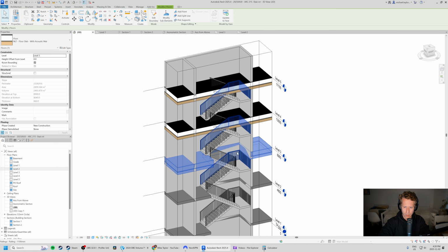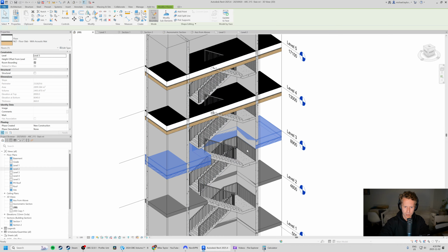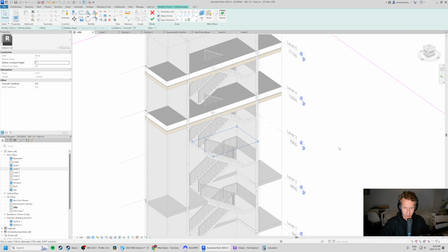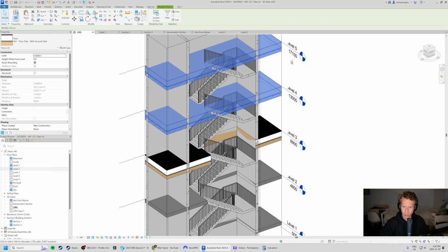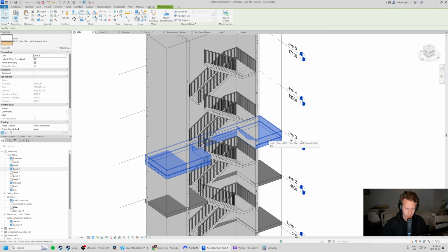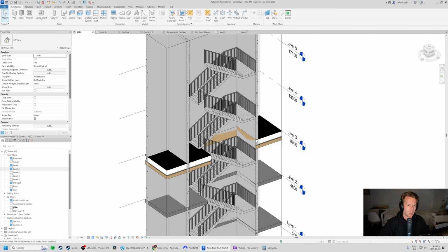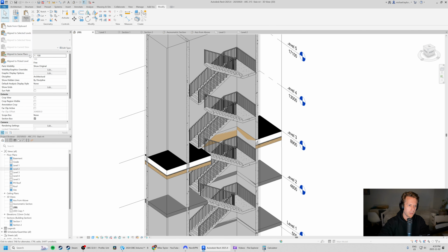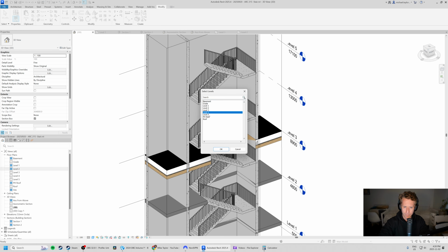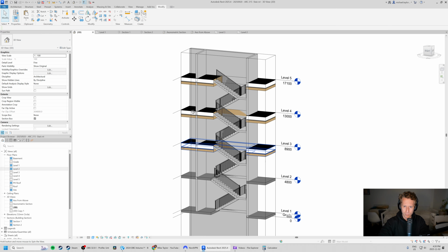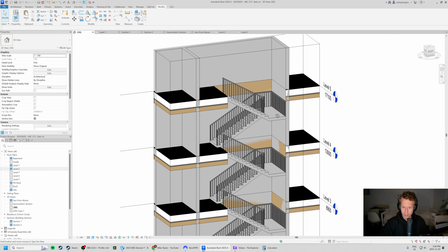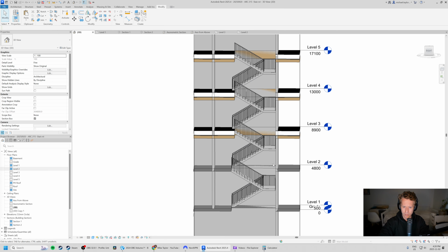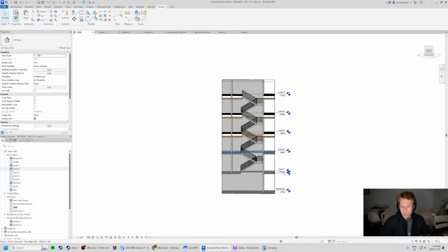I'm actually going to copy this one. So let's do edit boundary here. Tab select. I'm going to copy this boundary. Oh, I guess I can actually just copy the floor. I don't think I have any changes here. So I'm actually going to copy the floor, copy, and I'm going to go in and go to modify paste to each level, paste the selected levels, and I want to paste it to 4 and 5, and blam. So something like this. Ta-da!